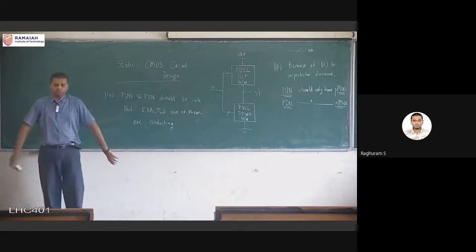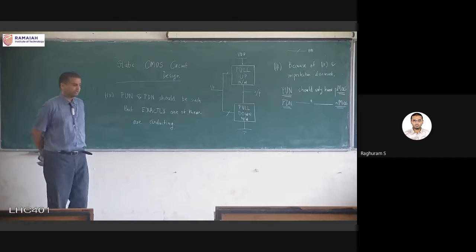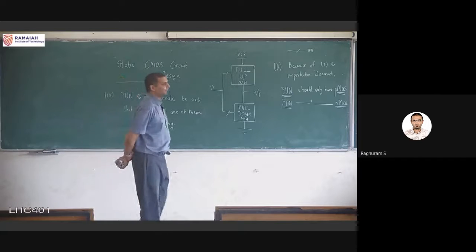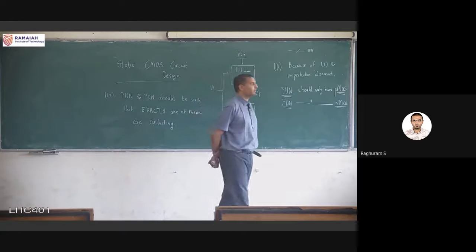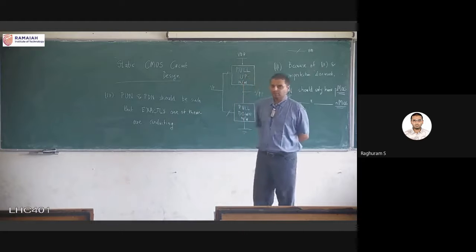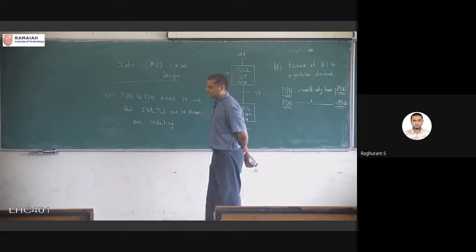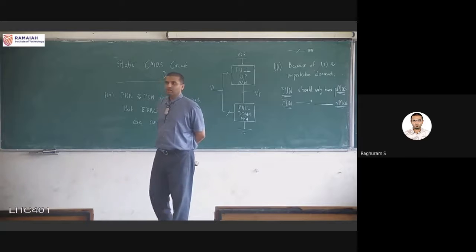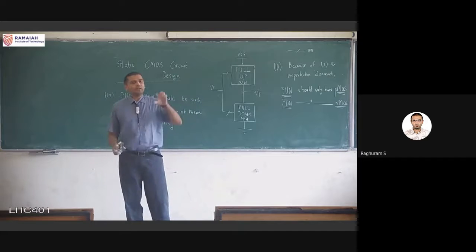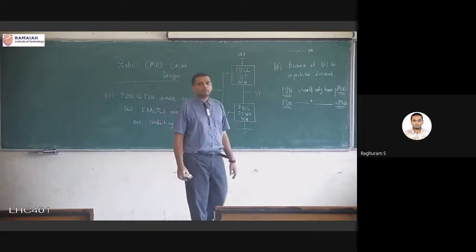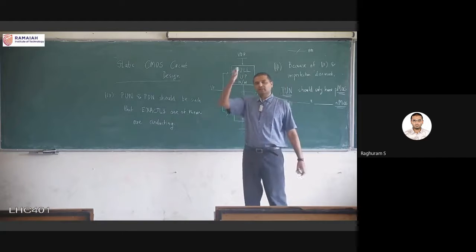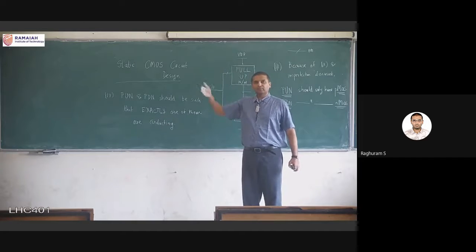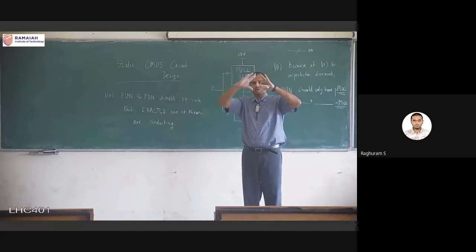Very important rule also. First, what is the meaning of a network being conducting? We know what is the meaning of a transistor being conducting, but a network being conducting just means that there should be at least one path. We have some examples we saw when we looked at the NAND gate, NOR gate, etc. Suppose a network consists of 3 parallel transistors.